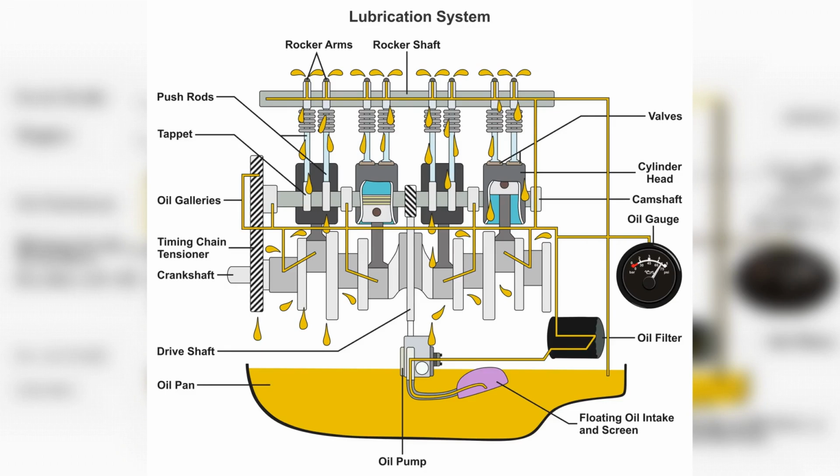For oil to circulate through the system, it must be pressurized. This is the function of the oil pump, which pushes the fluid through the system, delivering it to the rubbing surfaces, towards the oil pan, to the oil filter and further around the circuit. There are two types of oil pumps used in modern vehicles: gear pumps and rotary pumps. Gear pumps are characterized by a constant level of pressure created in the system. Rotary units are able to change this indicator depending on the needs.